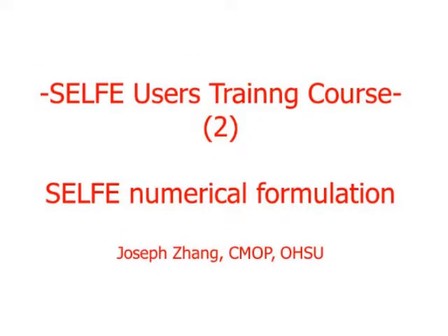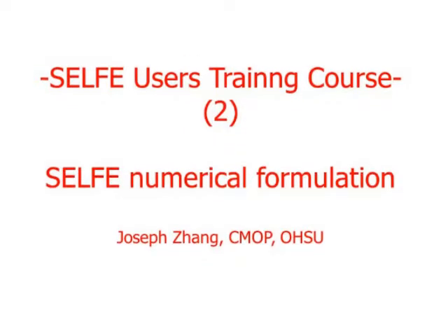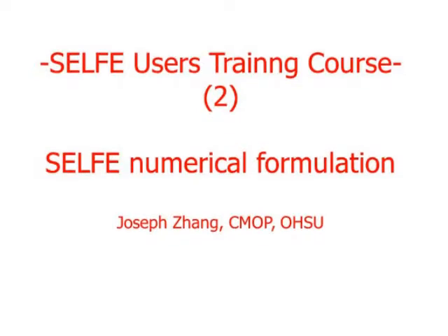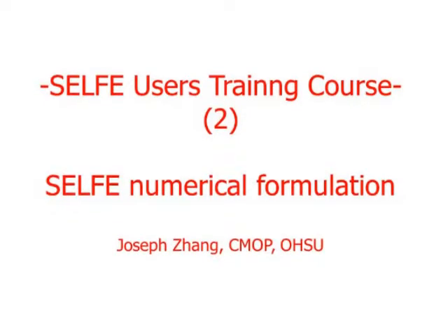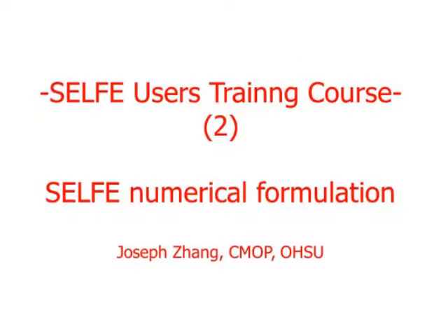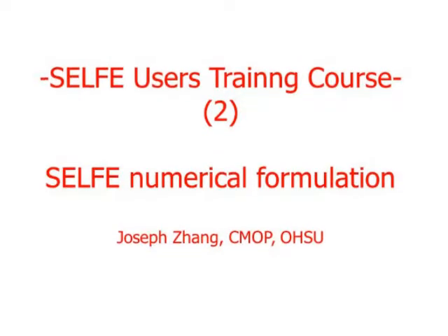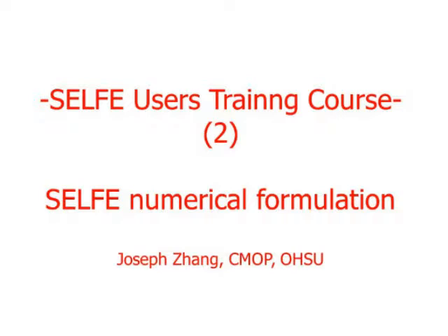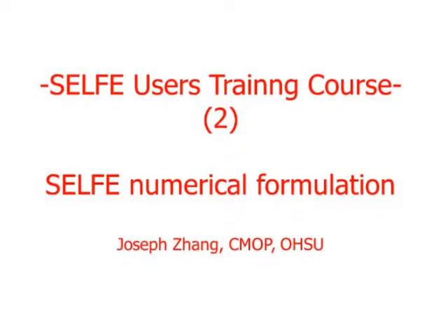On the other hand, if you do some manipulation, in the usual case you do integration by parts and utilize the boundary condition, then you are basically changing the weighted residual statement. In that case, you are using a weak formulation.